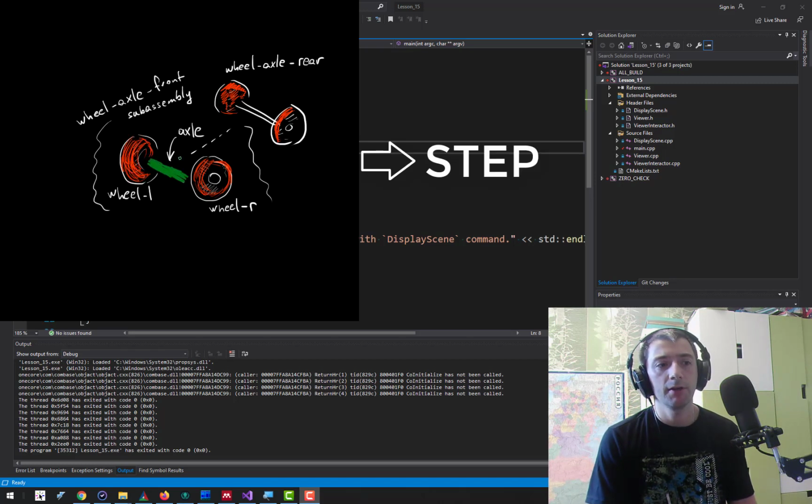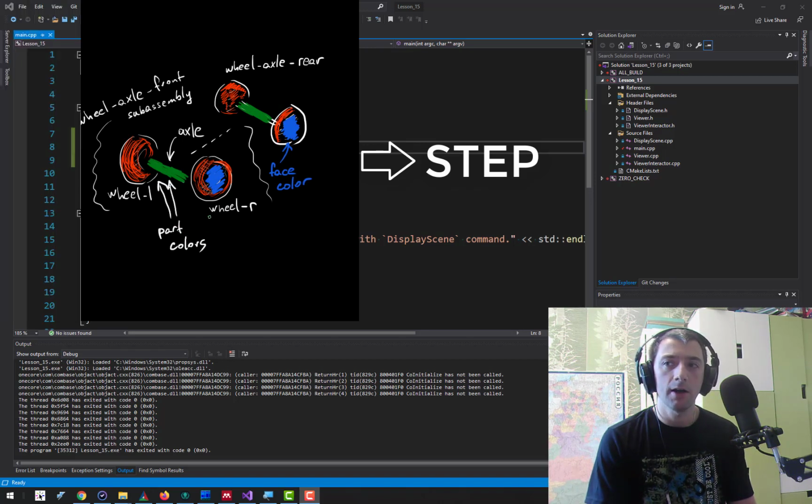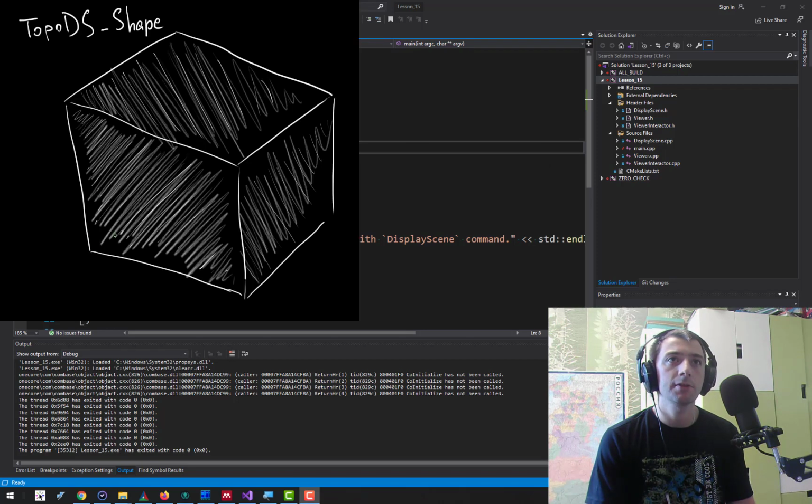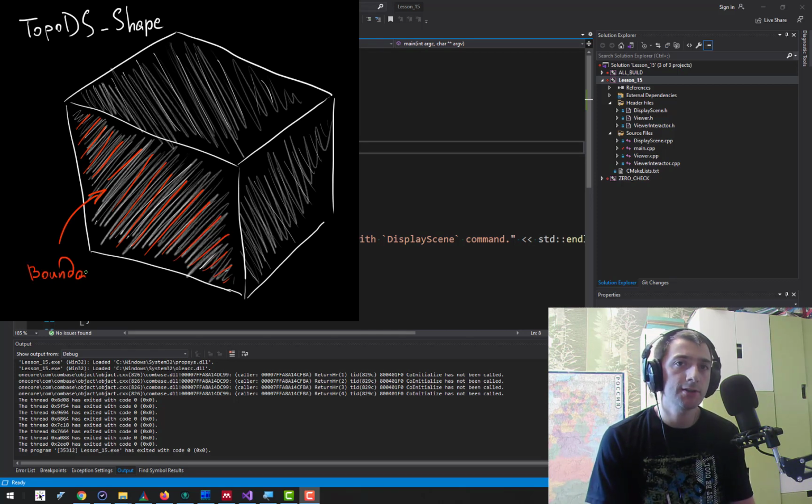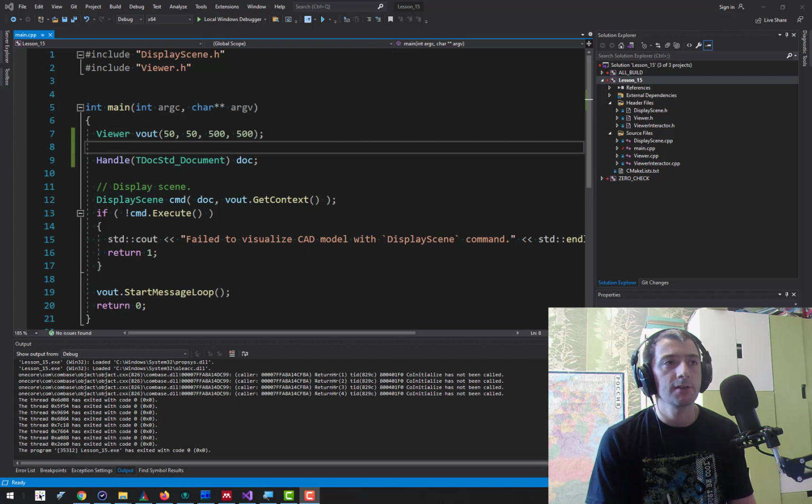And this is quite useful because this way you would be able to communicate not only the geometry of your product using OpenCascade, but also some metadata. And later on in the receiving system, you could take advantage of this metadata and define boundary conditions on specifically labeled boundary elements. You can define materials or subdomains. So this is something you might want to do if what you are developing is, for example, simulation software. So let's go ahead and try to make something like that.